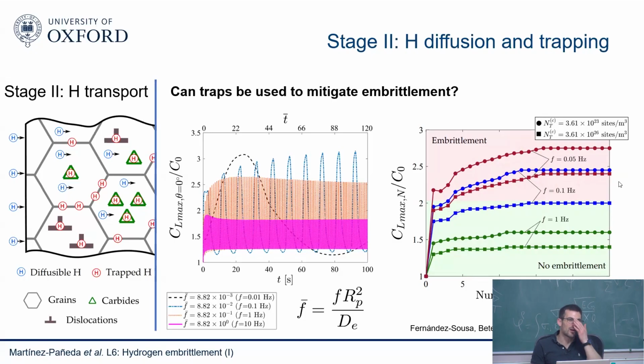So the key takeaway is that this idea is a bit risky and it will not be a solution for everything. But maybe in fatigue it can work, because the time scale that matters is the time scale of the loading cycle versus the time scale of the hydrogen accumulating near your crack. And you're not getting gigantic gains, because you can also not put carbides every nanometer, right? There's a limit on what you can do from the metallurgical side of things.